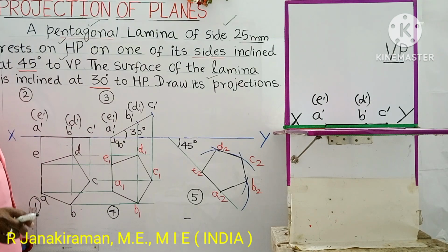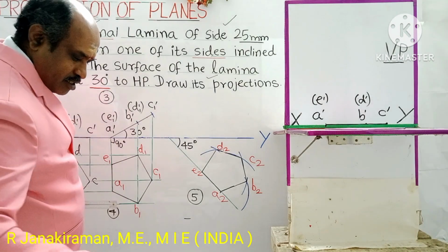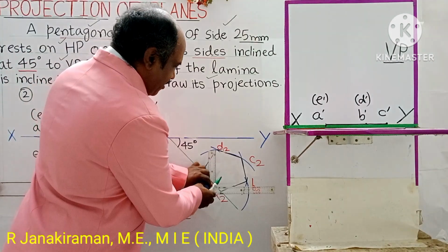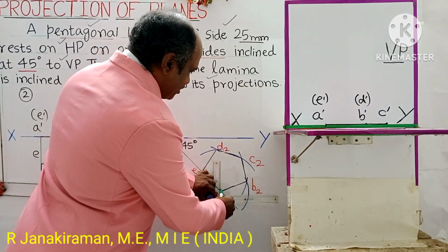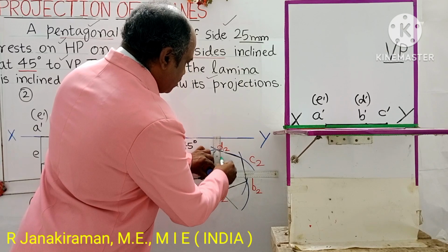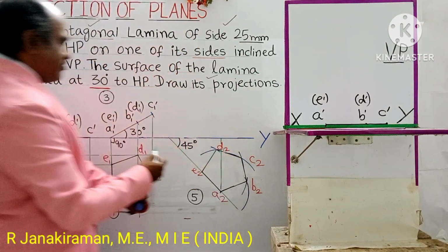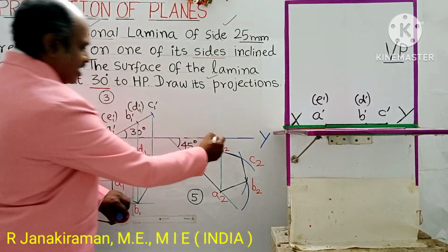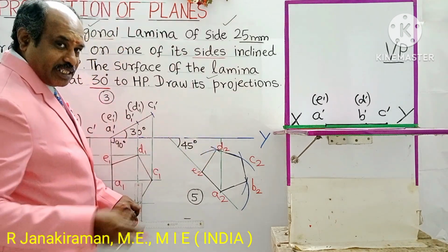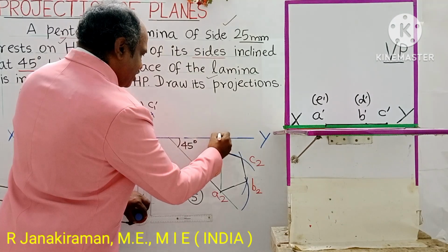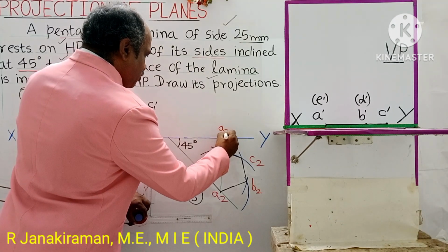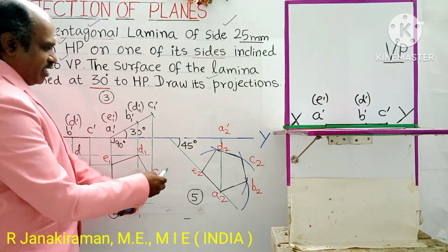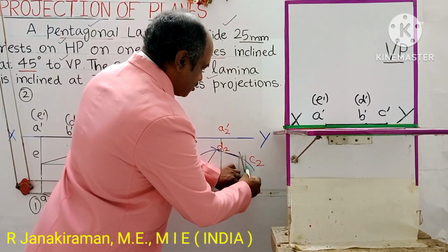Instead of going inclined, the diagram will be erect. Take a 2H pencil and, using the vertical scale of the drafter, from A suffix 2 draw a vertical projector where it intersects with the previous front view. Both intersect here and shall be marked. Then and there, give names to the points obtained so that you will not get confused. This is A suffix 2 dash. Next to A is B. From B, draw a vertical projector.